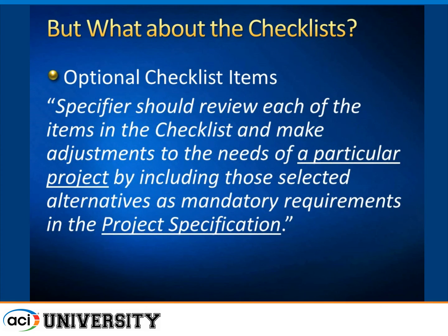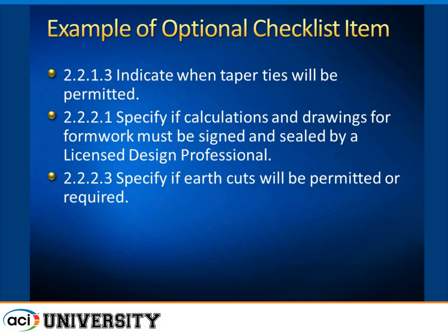But you do, once again, tailor it to a particular project and look at the alternatives. Here's an example. Indicate whether tapered ties will be permitted, or if you could in your spec actually require it, or if you want water stops on through ties, various things. Specify if epoxy coats would be permitted or required. So these are all optional things.